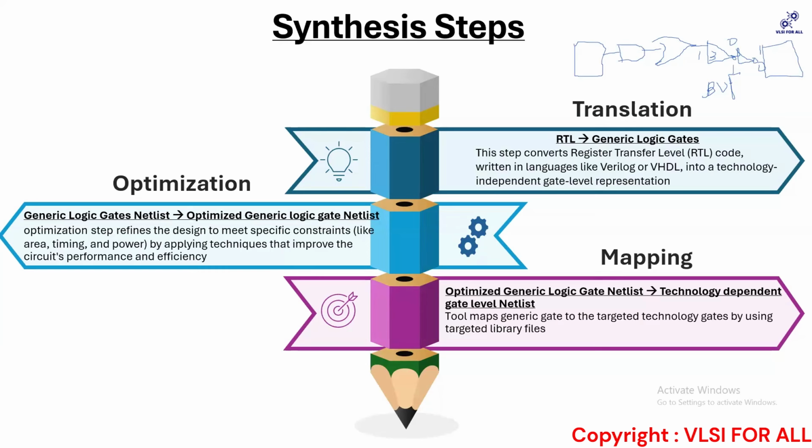They can even do the CTS netlist with the synthesized netlist, but the drawback is, see, the way the design gets matured, it has to do a lot of iteration to check it. Okay, and the time duration when it does it between a synthesized netlist and a CTS netlist can be high, while the one where you do comparison at placement versus CTS will be lower. Okay, because very minimal changes have been done in the design, right?